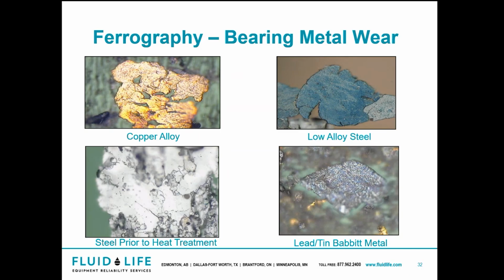And then you have another stress concentration because you have part of your material missing, and you've got this piece of metal floating around in your bearing. Now this is a snowball effect that can cause more fatigue wear, more scratching, more adhesion wear. Lots of different things can occur. So we're getting to the point where contamination is going to be imperative to keep track of.